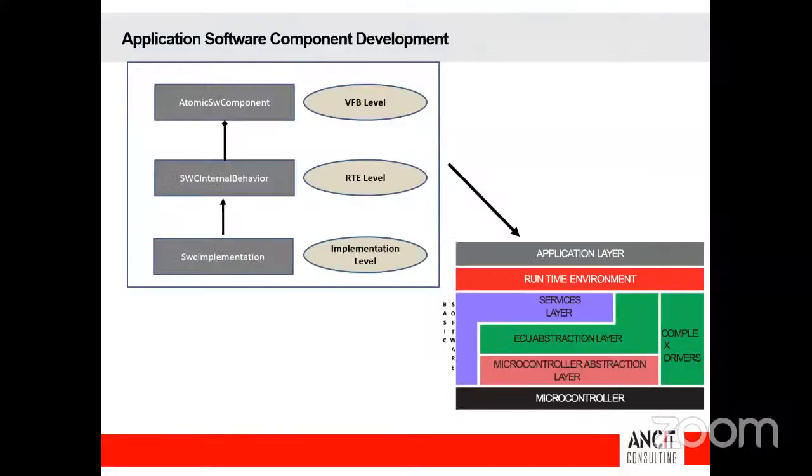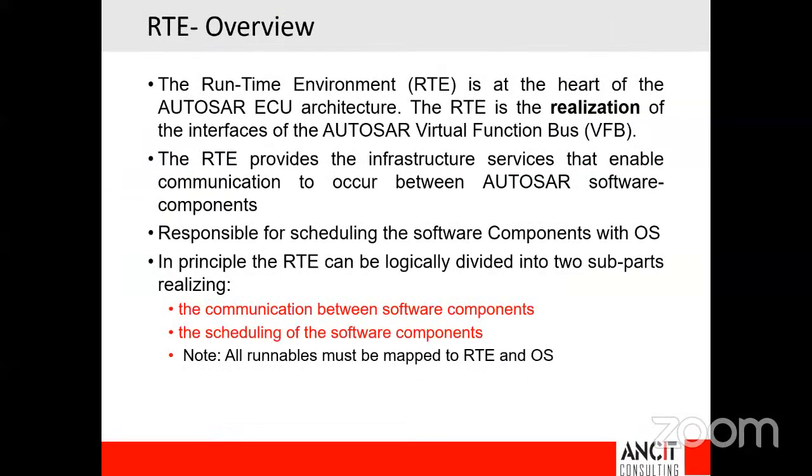Once we understand this whole high level design and we go to the RTE level design, after you design the runnables, there are two major responsibilities of the runtime environment, if I put it in very simple terms. One is that it is responsible for establishing communication between the software components. When you have variables to be passed between two software components, it is the responsibility of the runtime environment to make sure they are passed from one software component to another.